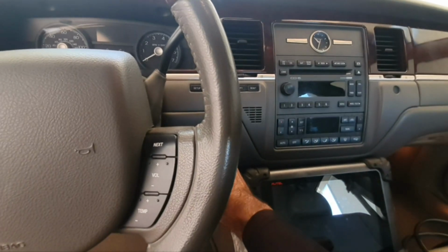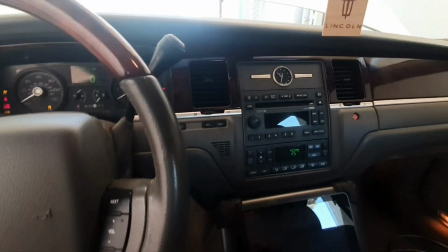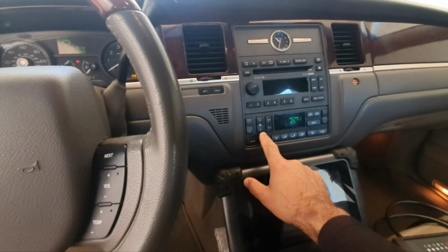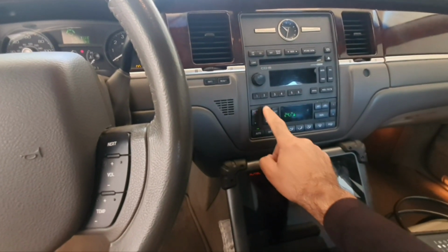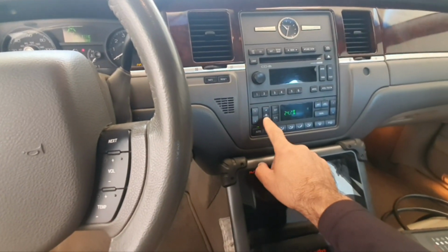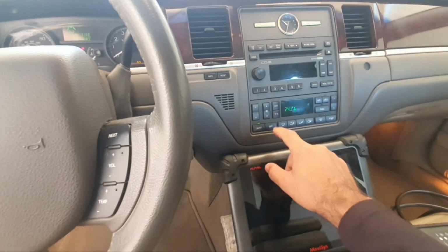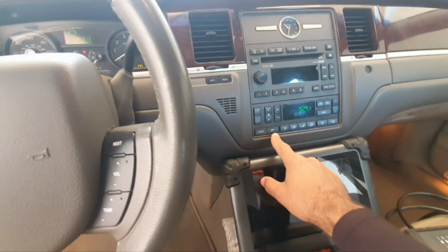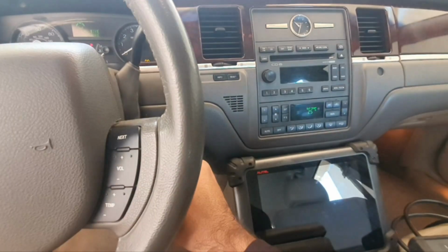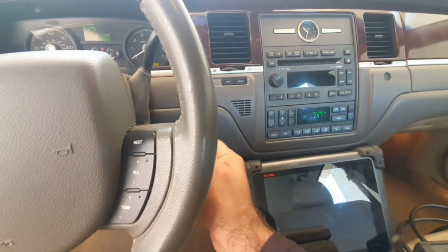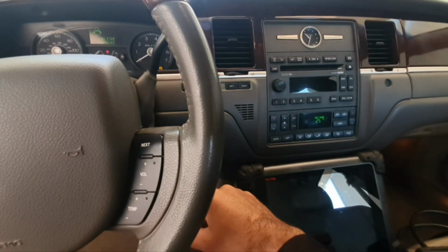Okay, so if I turn it on again, it starts running straight away without turning on the HVAC control module. Okay, so as you can see, I can turn on this control module and I can turn it off, but the blower motor will never go off. As soon as the ignition key is at run position, it starts blowing.